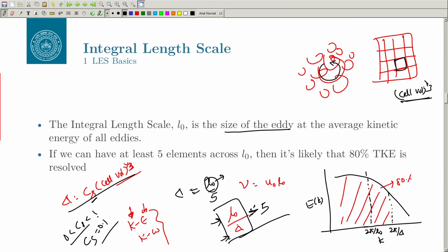Okay, you can make a contour and see what are the regions where you need to resolve. There will be some regions where this value is less than 5 and that you need to resolve, and once you do that, then that mesh is likely to be basically good for your LES simulation, and then you can make it probably 3 dimensional and do the LES simulation.